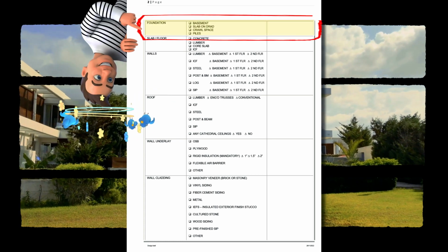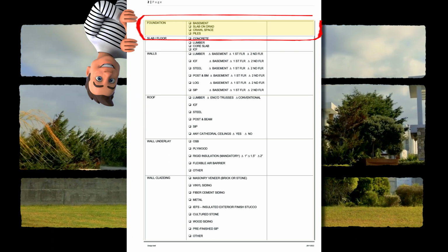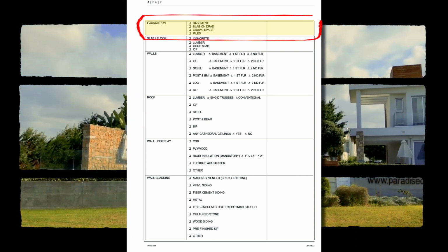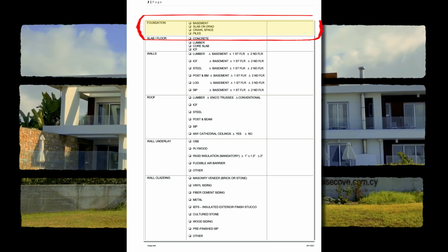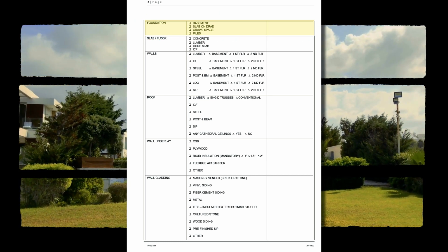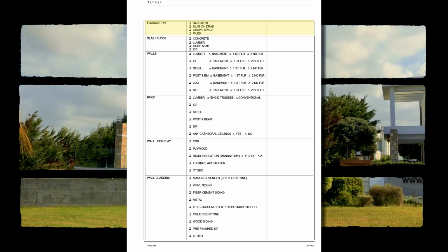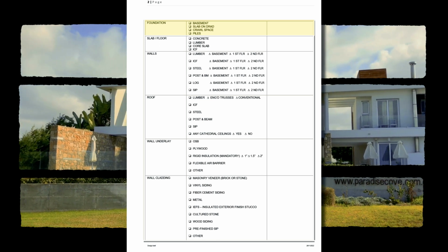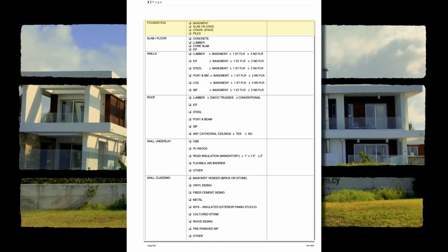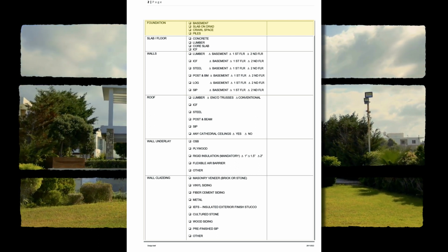For foundations, you will need to discuss with your clients the best option based on several factors including their budget and the cost of the various types of foundations, site suitability, soil type and bearing capacity, depth of the water table, type of foundation proposed. For example, is there a basement proposed? Is it a steep site, etc.?